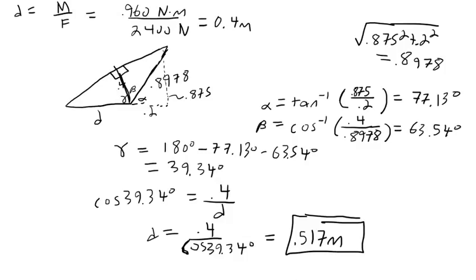Basically, we can do this different ways. We can do this as a problem of force components, or we can solve it two ways. One, a method of force components, then solving a really ugly algebra problem. Two, using the method of perpendicular distances, and then just solving a really ugly trig problem.